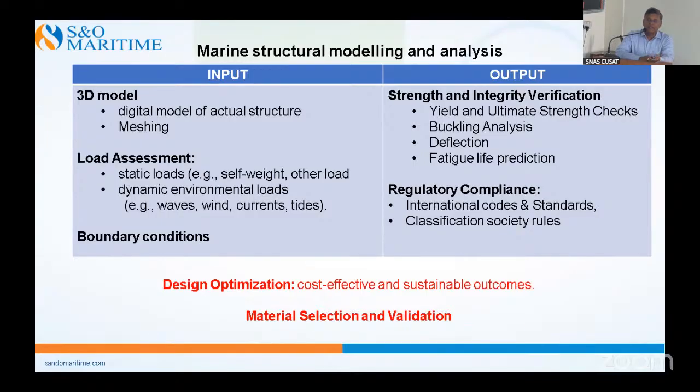So when we are doing a design, please have a look at how the market is, what the yard is looking for, and what the material availability is, and try to get it as optimized as possible. Because engineers, generally, tend to do the safe thing: instead of a 20 plate, let's put a 25 plate, and it's easy because there is no issue later on. And people don't realize what the difference between 20 and 25 is, because they have not seen it actually.